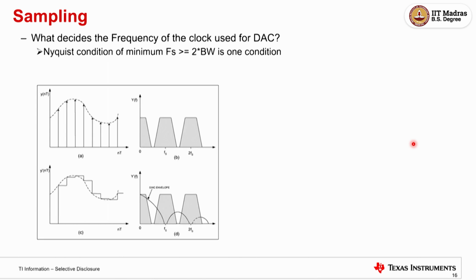Okay, similar thing, so I'll skip. The DAC is also the same thing. When you have digital information, you have copies, and if you don't run the DAC at twice the frequency, the same thing happens. This comes and folds here. So you need more and more rate so that you have a faithful representation of the signal rather than all the copies or some bad representation, because you're trying to represent it over time. If something has moved faster within this, you will not represent it. You have lost that signal. That's where this higher and higher rate frequency comes in.